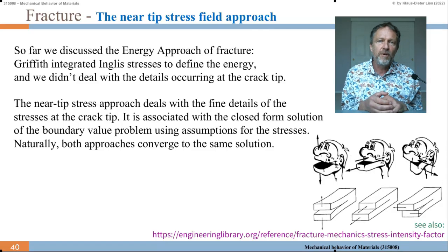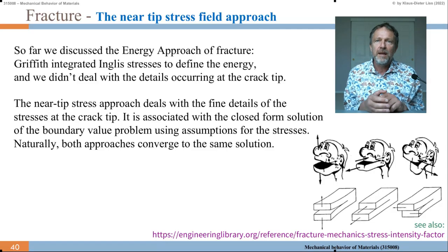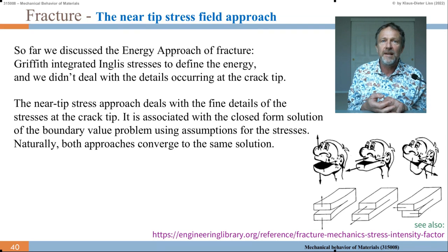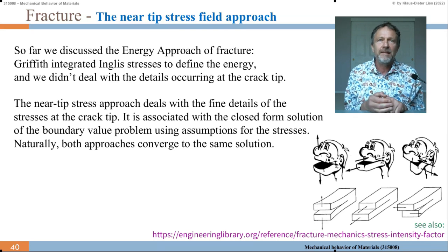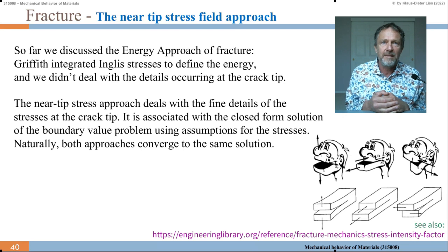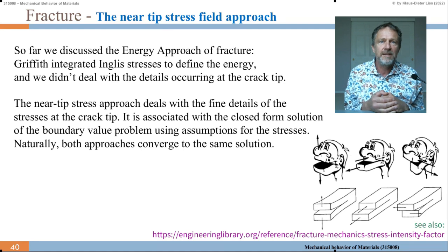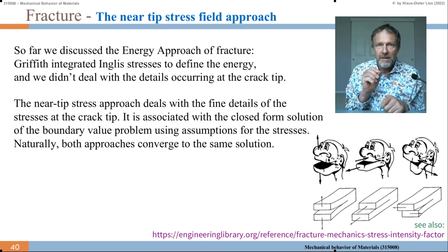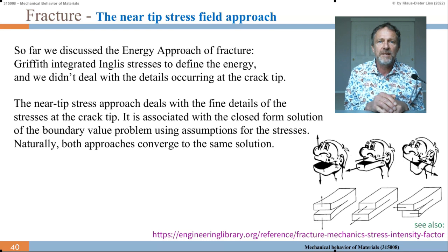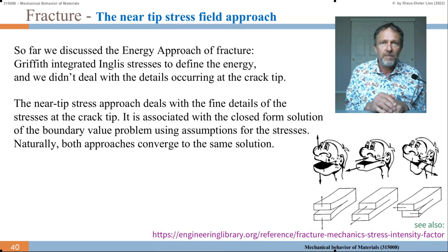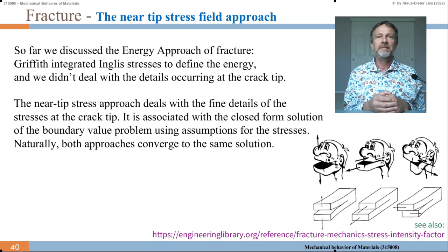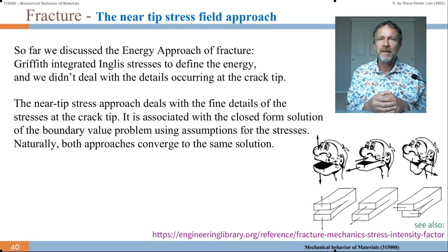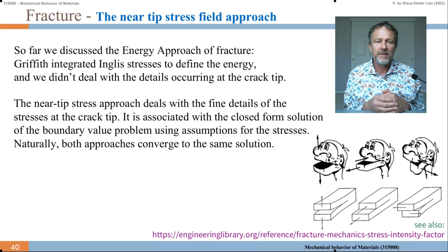I have given you several approaches, including the stress energy release rate for the propagation of cracks. They had the disadvantage that the theory has a singularity when the radius at the crack tip goes towards zero. Then the stress is going to infinity, and of course, that cannot be. Something will happen at this crack tip, so that we will have some plastic deformation.